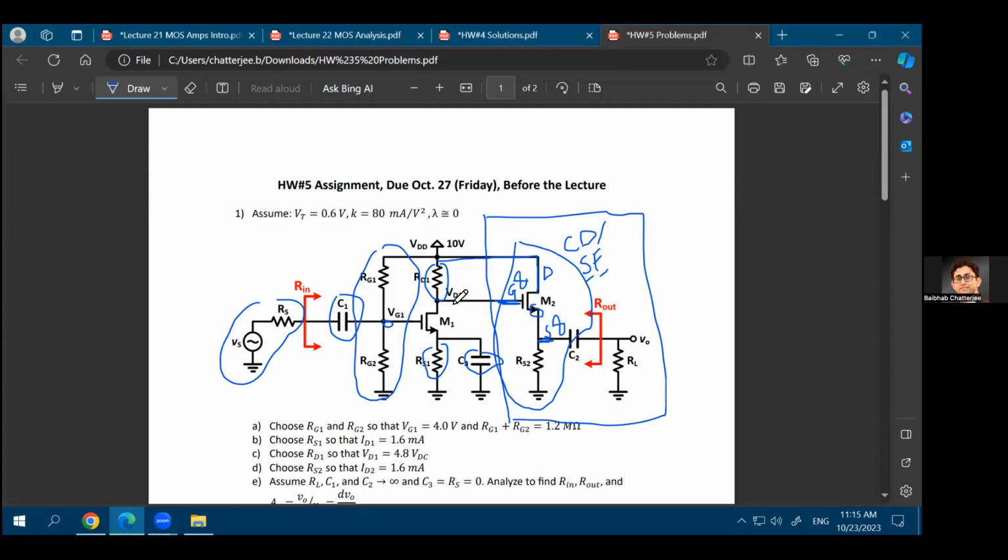So you know that the input impedance of the oscilloscope needs to be very high, so that you are able to see the voltage that you want to see from the circuit. But if the oscilloscope is configured in a 50 ohm mode, or if you want to see the signal in a spectrum analyzer or any other instrument for which the input impedance is 50 ohms, you will see that it's very hard to drive that instrument from a single stage amplifier.